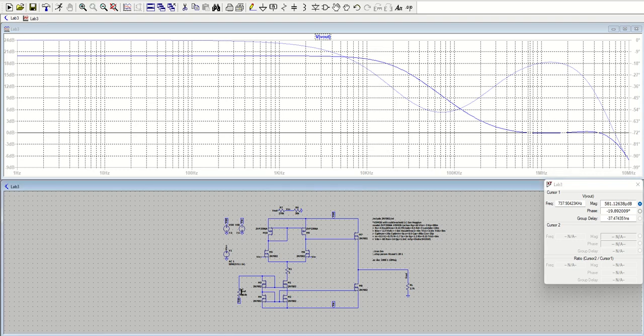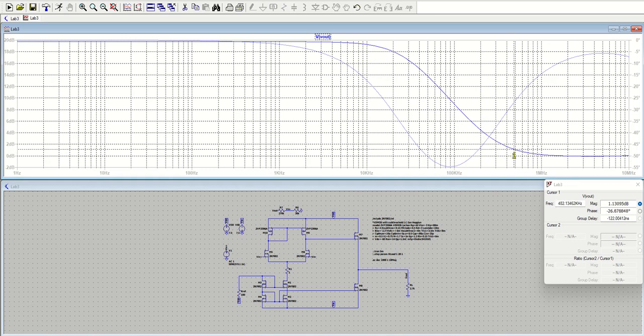Again, I wanted to point out that by increasing the total current and extending that linear region, which I talked about in the previous video, we can remeasure right now and see what we get. So 127 micro dB is practically 0, and we're getting negative 8.9 degrees. That increased the phase margin. We were at negative 19, and we increased it to about negative 8.7 degrees. So by increasing the total current, we're able to create a more stable amplifier.